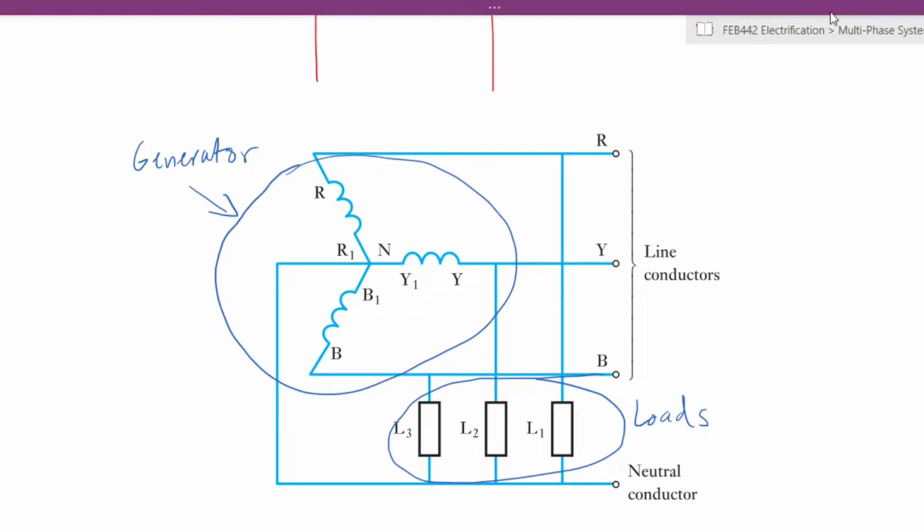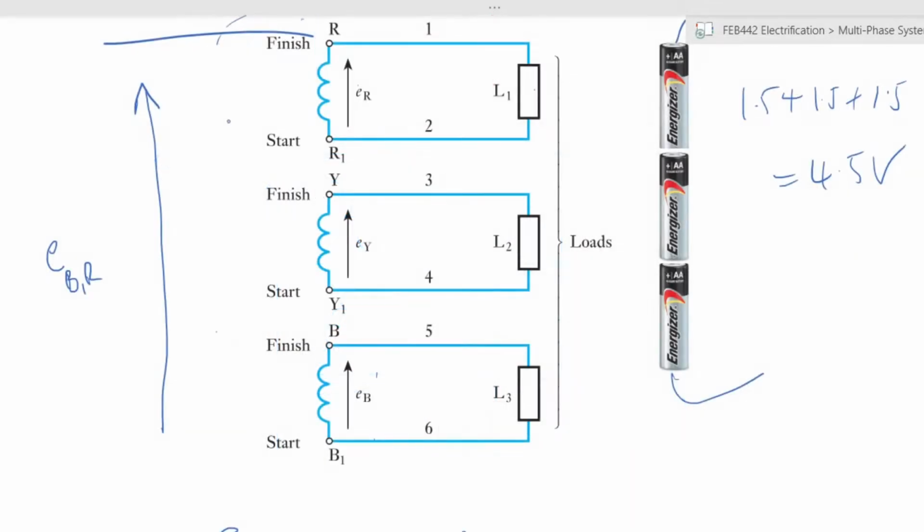So if you go back to your individual generators, when you have your windings that are connected internally within here, the voltage that is available, so let's say EY here, the voltage at this point, before you take it from the machine, this kind of voltage is called a phase voltage, because that is the voltage that is seen by the windings themselves, right?